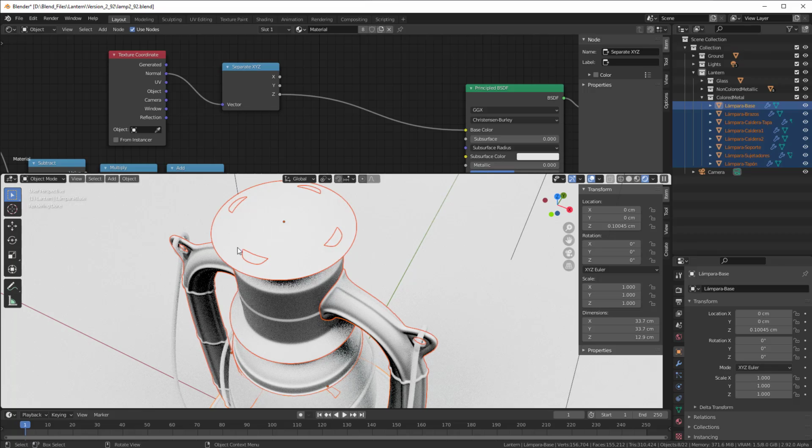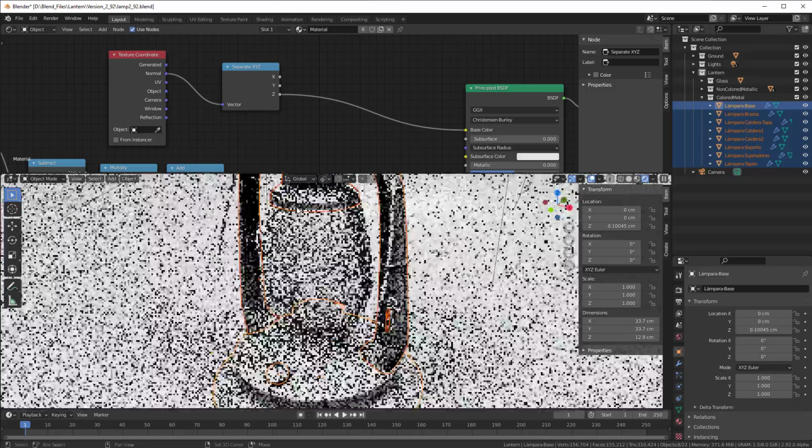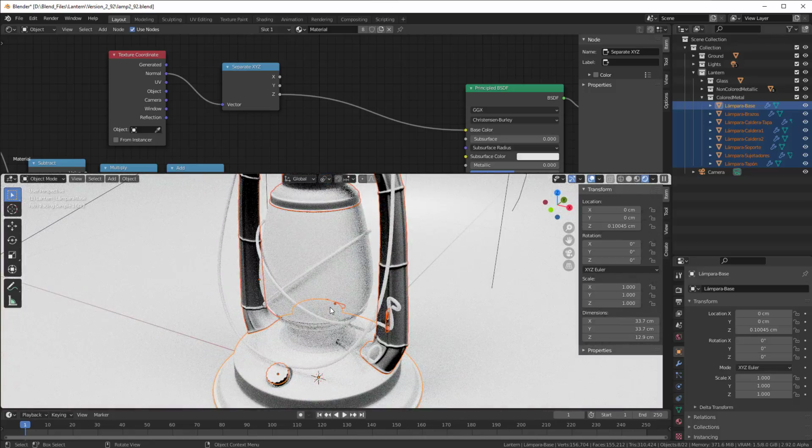By combining this and the vertex paint, you can then create something that is unique for where the dust will be. So perhaps you don't get so much information from the vertex paint that you will have dust here on that part. It will more be on the edges, but if you have an object that is standing for a while, you know that this part will have a lot of dust.